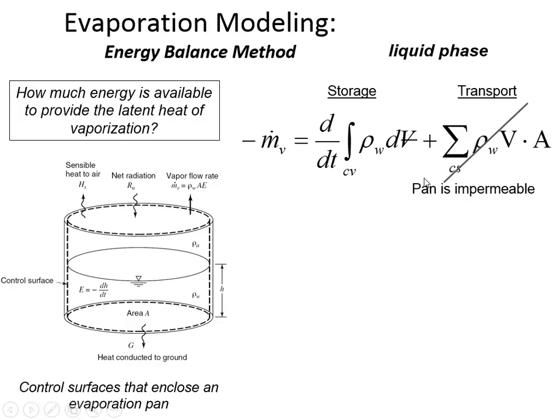And the easiest thing to estimate evaporation on is a metal pan. Because out in nature, if you have a puddle and you want to find out how much that puddle is evaporating, it's hard because some of the moisture is going to be infiltrating down into the soil. And so, when you watch a puddle in sand disappear, you may not know how much of that evaporated and how much of it had infiltrated.